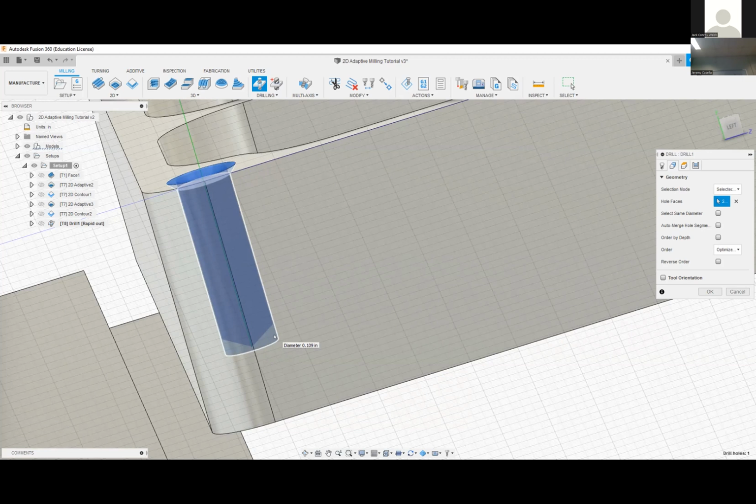When you design stuff, keep this in mind, right? Quick design for manufacturability thought. No one's drilling with flat bottom drills. Very rarely they are, they exist. So we'll go ahead and put the tip to the bottom there. So you're just going to lose a little bit of extra material. If you have to worry about breakthrough, that's something to be worried about.